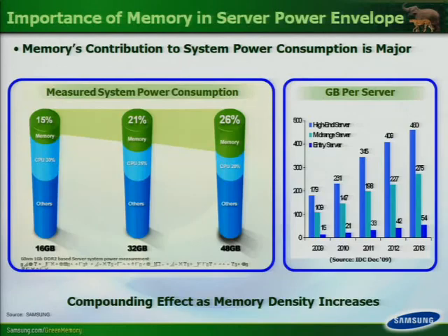When you look at the servers that were built prior to the launch of Intel's, for example, Westmere, or AMD's Opteron technologies, pretty much you're in an environment of legacy equipment that has been using either FB DIMMs, fully buffered DIMMs, or even much older technologies. When you look at the amount of power consumption that this technology has in the system, on average, if you're even looking at a 48 gigabyte system, the contribution of power in the system is about 26%, as opposed to 20% for the CPU.